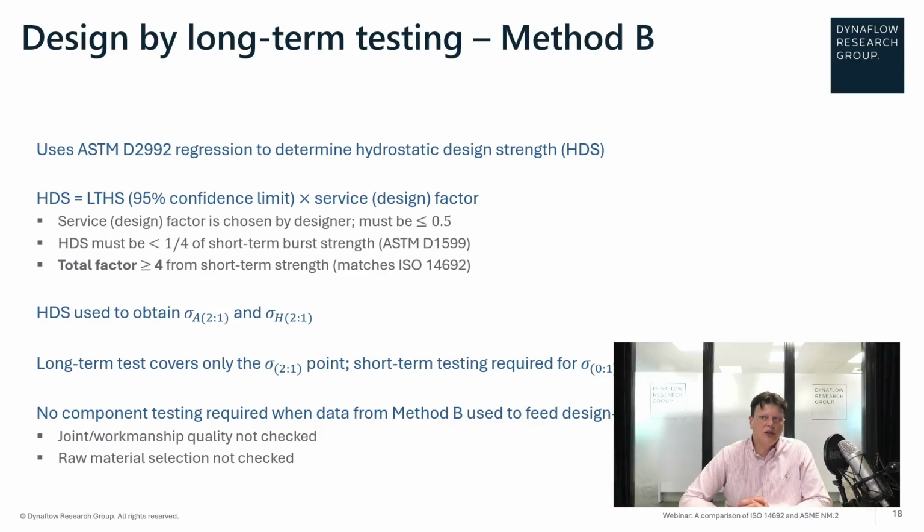And the design factor is chosen by the designer, but it must be less than 0.5 of this long-term hydrostatic strength.